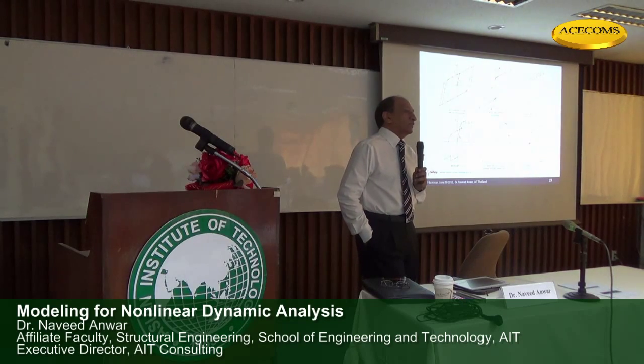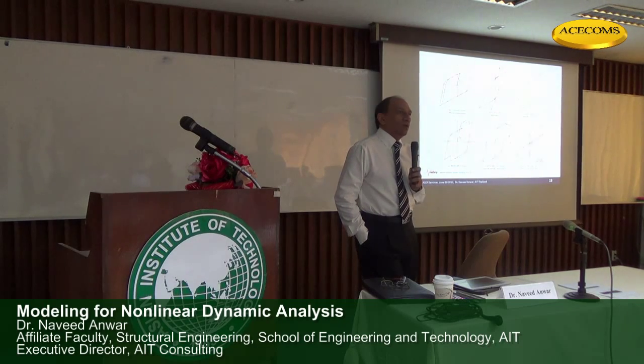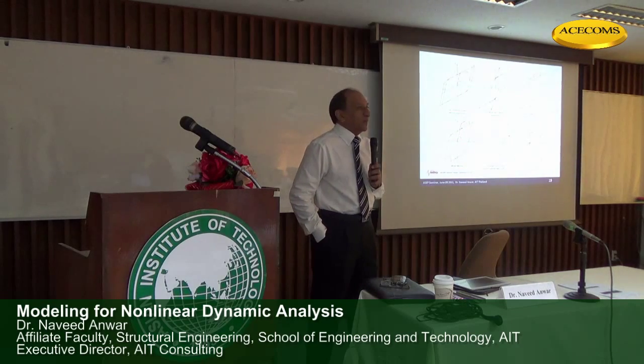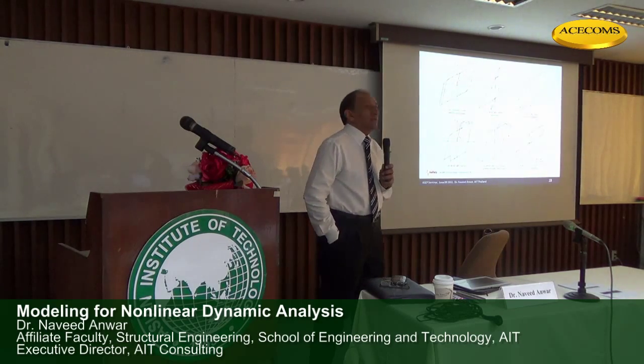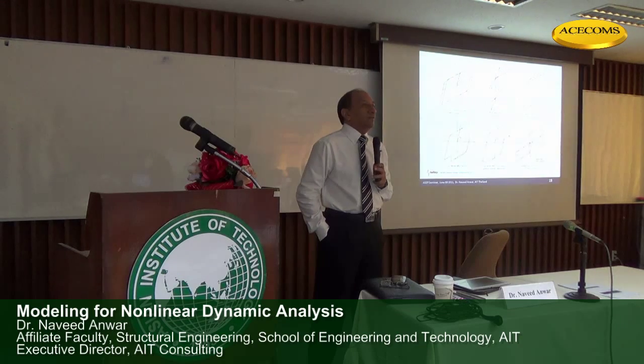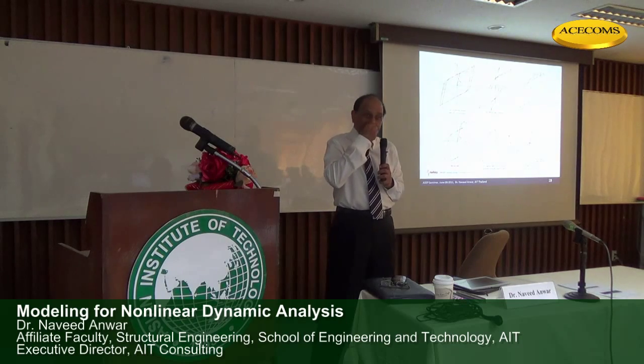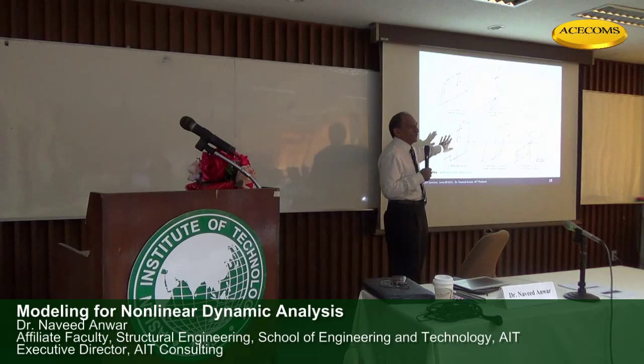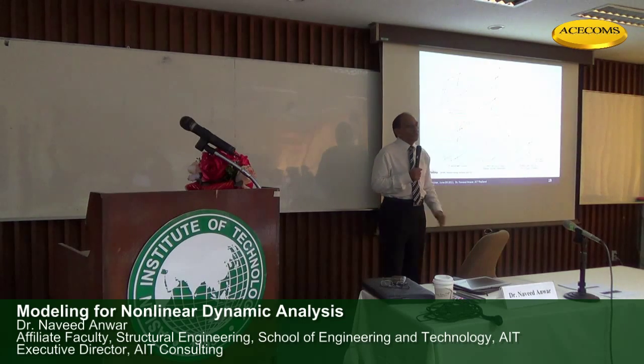Normally, the programs which are research oriented, for example OpenSees, or Ruaumoko, or programs like that, have much better models than commercial programs like SAP or even Perform, which is considered to be the best program for commercial application. They have a limited number of hysteretic models, which is really a shortcoming.